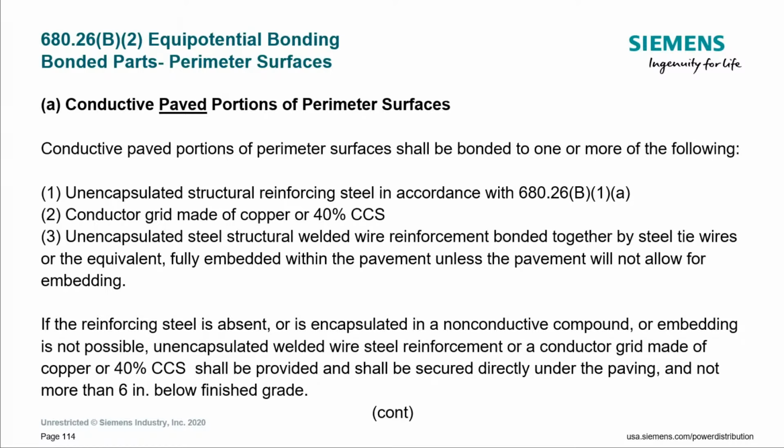Or if it's not there, or maybe it's going to be a concrete pour, but the concrete is going to have that fiberglass mixture in it. The fibers, so it's not reinforced by mesh and not required to be reinforced by rebar, more from a building structural standpoint. It's been determined that fiber mesh, where after they pour it, if you went there the next day, it looks like it needs a haircut. The fiberglass fibers are kind of out there. So that would not require, maybe from a design perspective, to have rebar in. And the code is trying to recognize this.